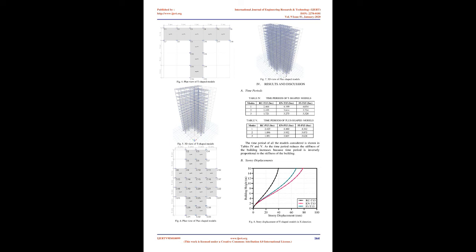Rajendra R. Pawar and Vinay Campbell [6] presented a paper comparing composite and RCC buildings. Two G+15 residential buildings of composite and RCC structure are analyzed and designed using ETABS with different storey heights of 3 m and 4 m. It is found that the depth of beams in the composite structure is less than in the RCC structure, which also reduces the sizes of columns in the composite structure, giving smaller sections for the same loading in beams and columns. For the same structure, when the floor height is increased, it does not make big changes to axial forces and bending moments.